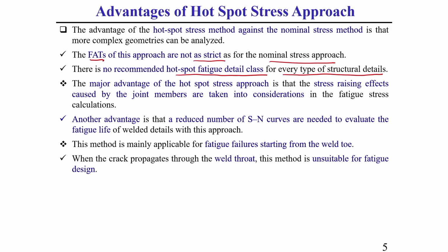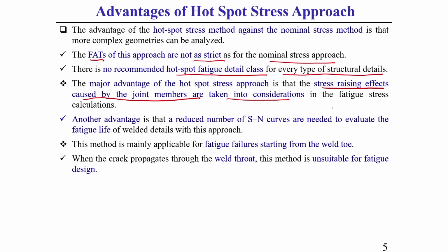And the major advantage of this hotspot approach is that the stress raising effect caused by the joint members is taken into consideration. You should keep this in mind. Let us say we are joining one web with one flange. The effect of these joint members is considered in the hotspot approach, and that stress raising effect is also considered and used for fatigue stress calculation.